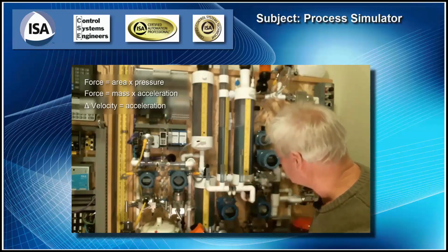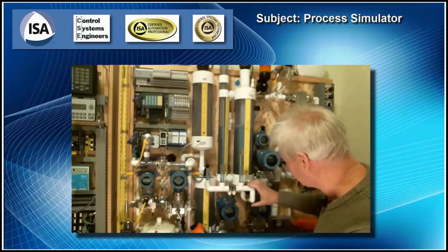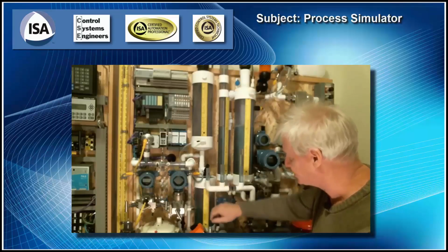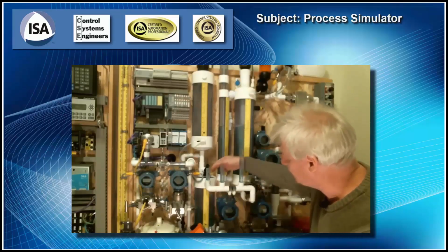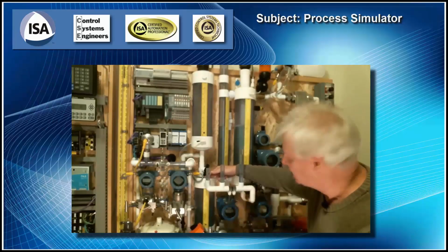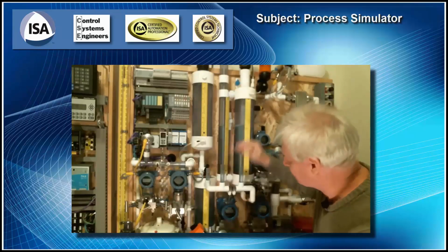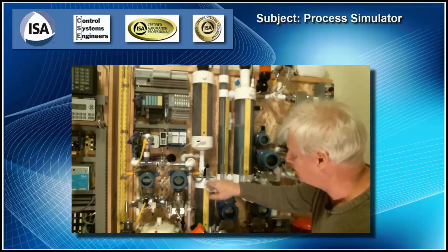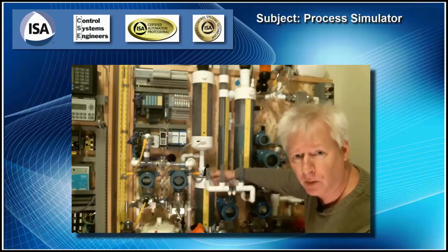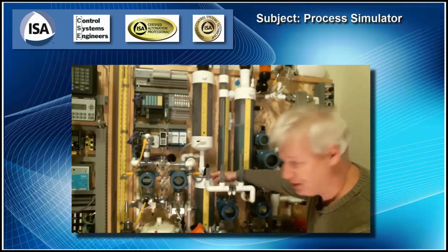This piping system is just like an electrical circuit. These are resistors. The valve's a resistor, the 90s are a resistor, the pipe is a resistor, this 90 is a resistor, and behind here, I actually have a little orifice. It's a small washer, and it has a hole in it, and this resistance acts like a long piece of pipe. That's why the water stands up here instead of being at zero going out, because we know at the end of our run we have no energy left. We've used all of our energy, going from maximum energy to zero energy.